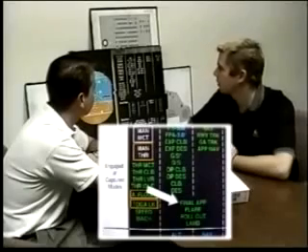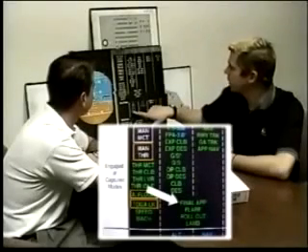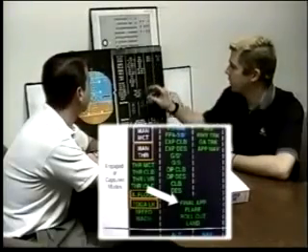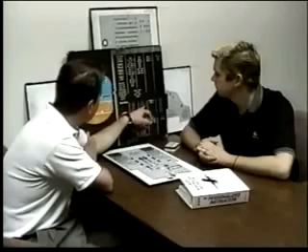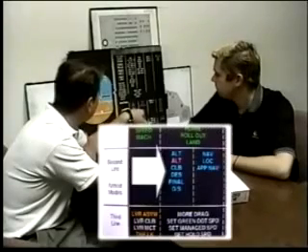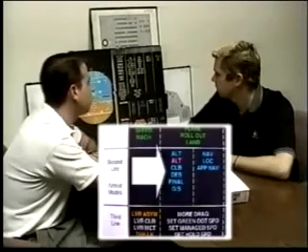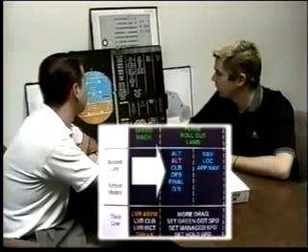Final approach? FINAL APP is a combination of final and approach nav, and it just means that the entire LNAV VNAV portion of the approach nav approach is engaged. And what about the items that you see in blue down here? For example, blue ALT, blue glide slope, blue LOC. Those are armed, and they're on the second line, and they just mean that those modes are armed.